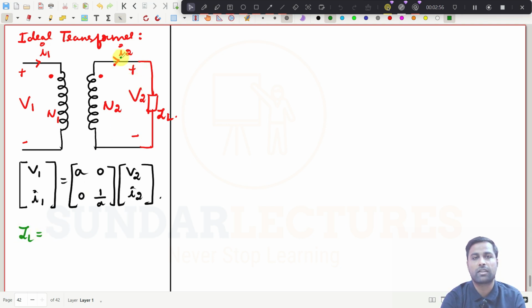See this one, the current is coming down here. This is V2, from plus to minus it is traveling. Then obviously it will be V2 by I2, maybe small letters, v2 by i2. This is ZL. So what you can represent here, try to understand me very clearly: this is the representation of the ideal transformer in terms of ABCD parameters. I have written this in ABCD parameters. This is V1, I1, and this is V2, I2.